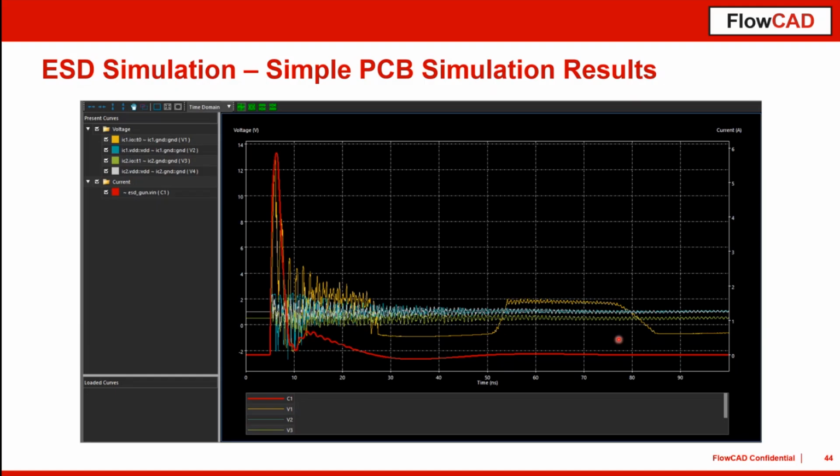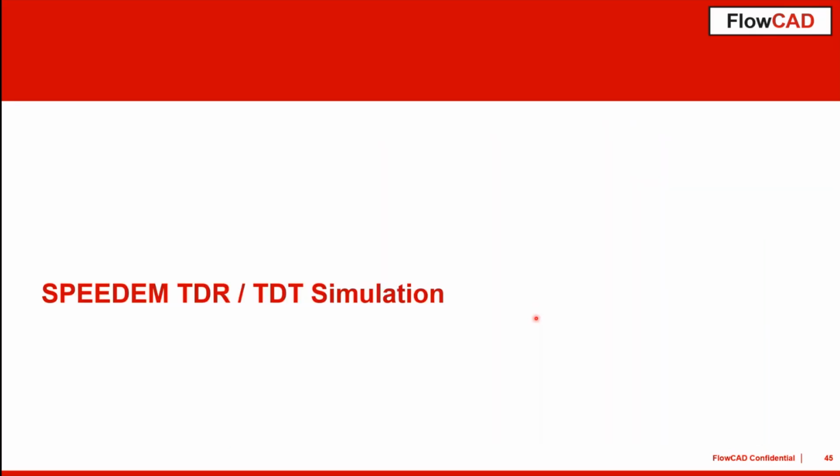And if you change some values of these ESD protection diodes or capacitors and so on, it might be possible to change the values here and see the improvements of the complete ESD protection. Well, I think this could also be very helpful to avoid damage of your PCBs in the real world when you go into your lab measurements.